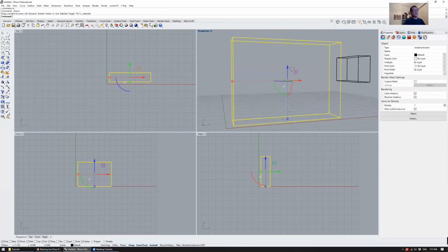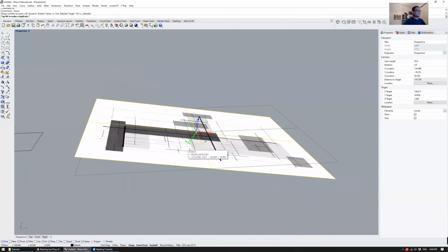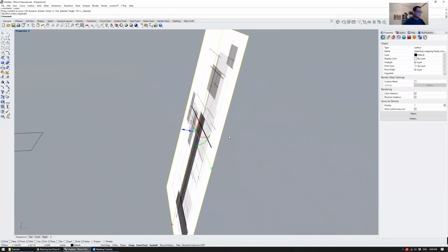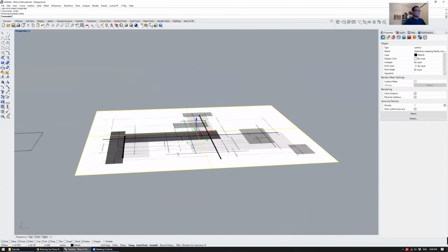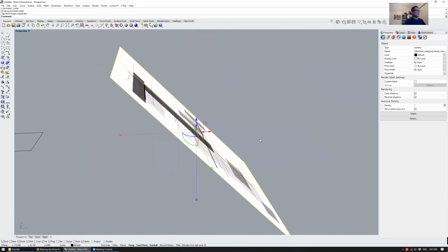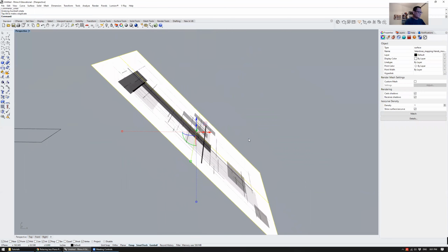These arcs are rotation arcs, right? So you can rotate things on a center axis using that if you want arbitrarily. As you're pushing and dragging the arc, if you hold down shift, then it will snap to 90-degree angles. This is useful if you're trying to just flip it or turn it 90 degrees. Or of course, if you click on the arc and you put in 45 degrees, then it will move it 45 degrees.